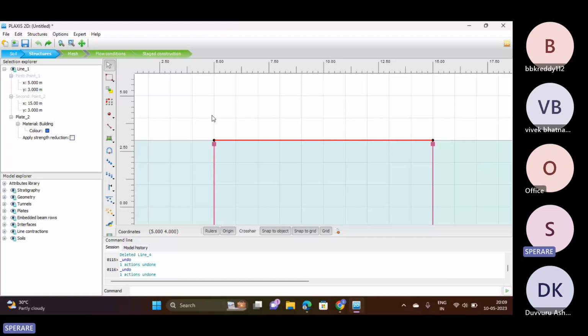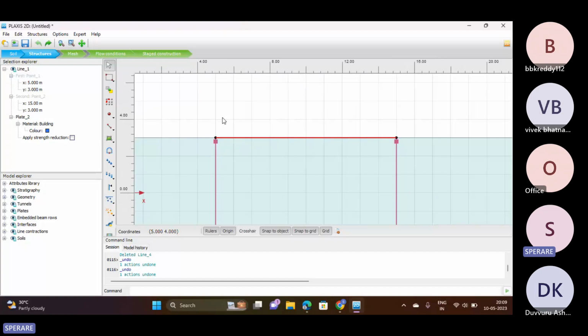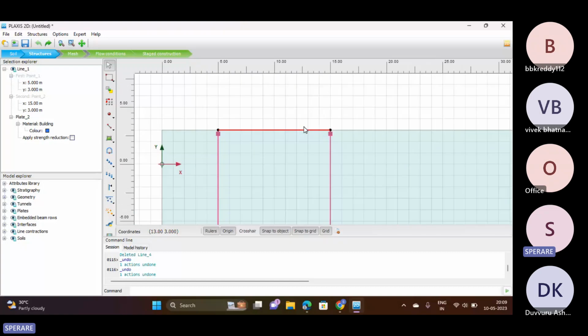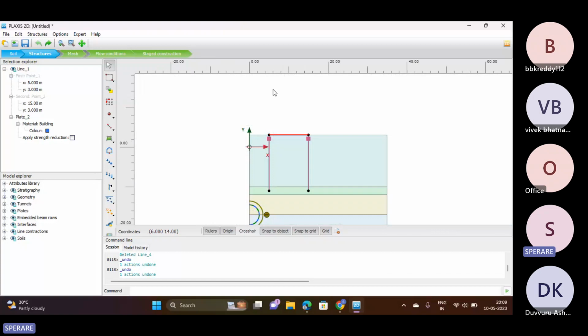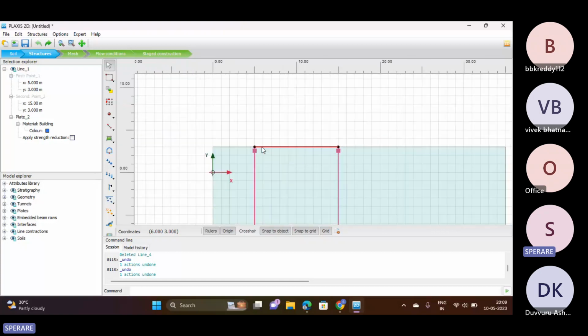It's simple. So we already know how to create material properties. We have already seen that. That's why I'm just going in a fast way. So this is where it includes the complete building material properties. Okay, it is just an assumption, guys. Instead of building the whole construction of a 5-story or 10-story building, we were just using that particular plate element as a building, and this particular load will be distributed to these particular piles.